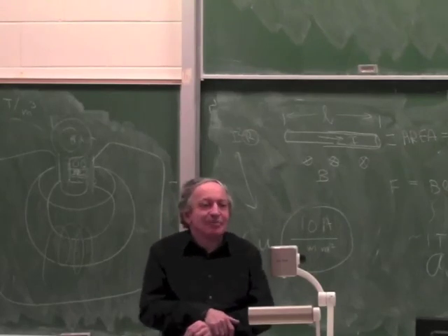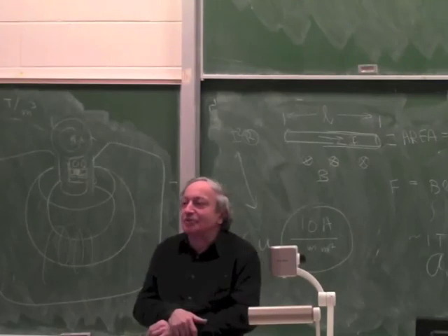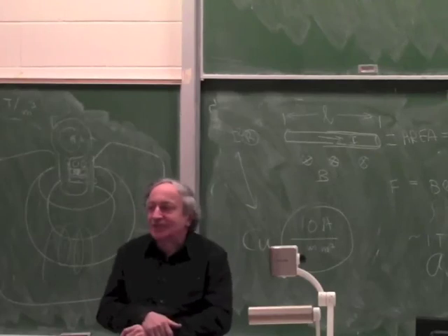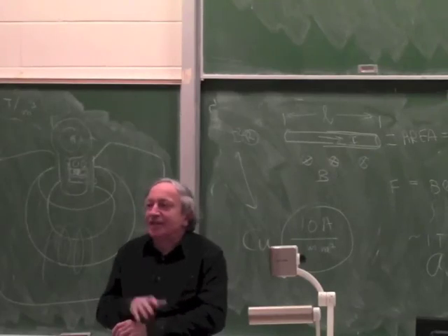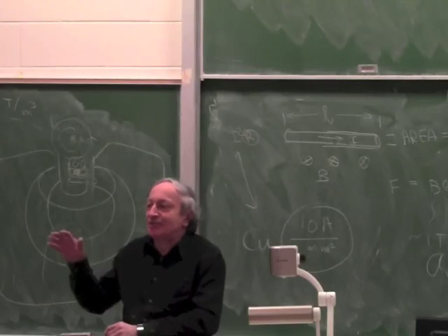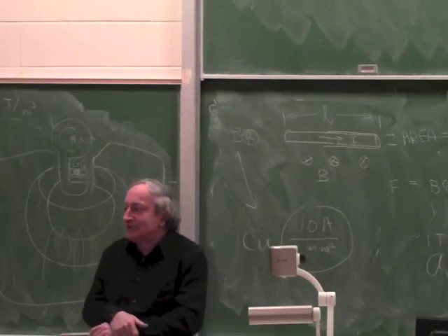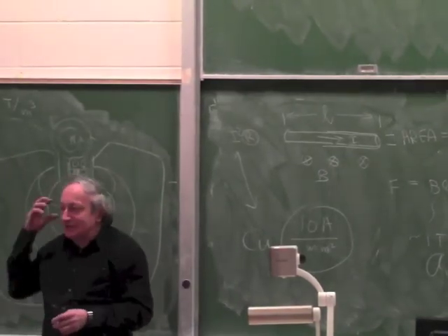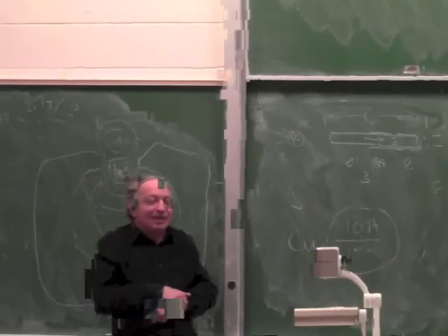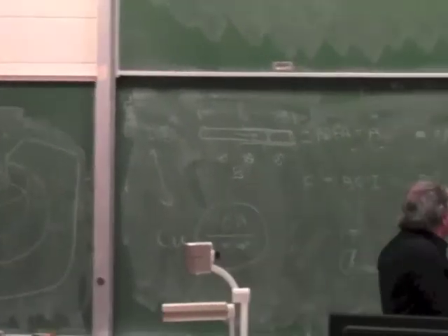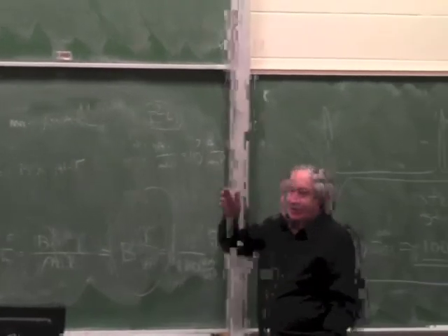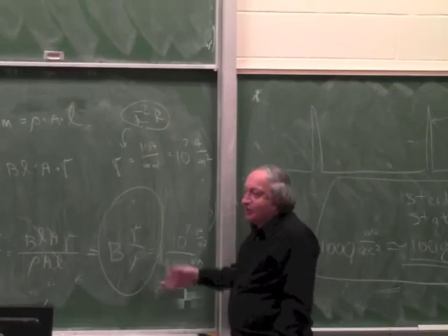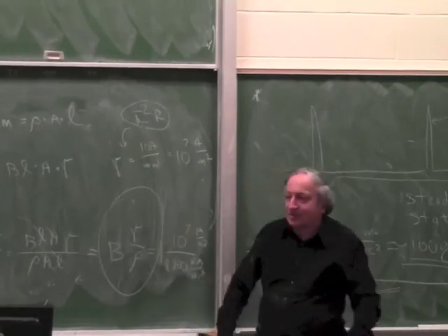Can somebody think of an example? Where do you see aluminum wire used today? In actuators. High-end speakers. If you buy the highest end speakers, the coils inside are aluminum. Because in a speaker, this extra 30% means something to high frequency and so on. But really you can't gain much. Silver gains you almost nothing and costs a lot more. Aluminum gains you a little bit, but because B drops a bit, the overall gain is maybe 30%.